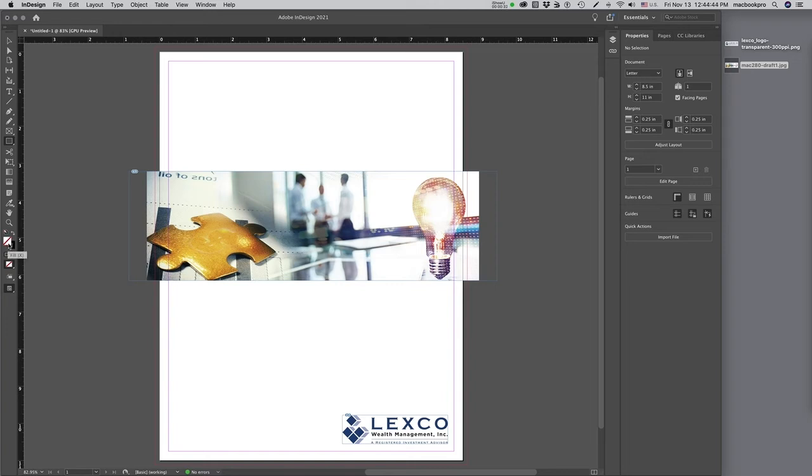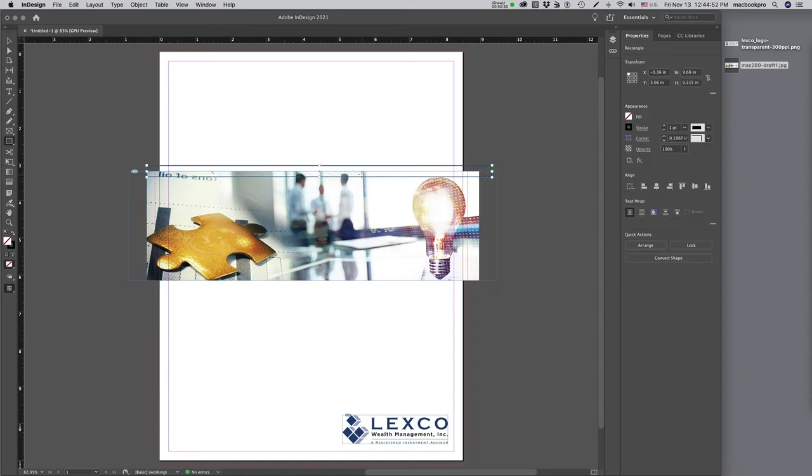And I can change the colors of this very easily, but first I'm going to just draw it. So once I've drawn it, I'm going to grab the selection tool so that it is selected, and I can go over to the appearance panel and change the colors. So I don't want to have a stroke on here, so I'm going to change that to none.